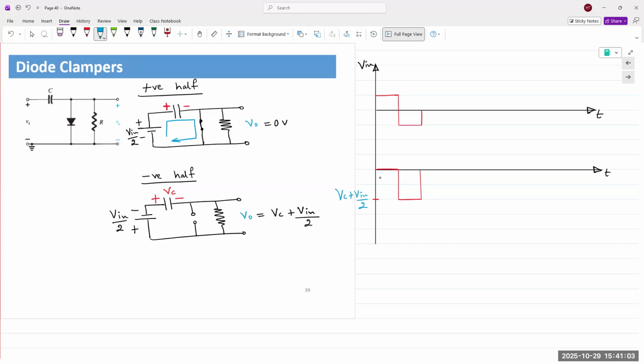So when the capacitor charges, variation in what? You're talking about the transient portion? It's a very good point. The question being asked is, what about the transient portion when the capacitor is charging up? The answer is the diode resistance is very, very small. Even in real life, the diode static resistance is going to be very small, so the capacitor can charge very quickly.